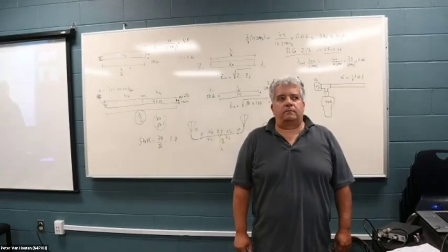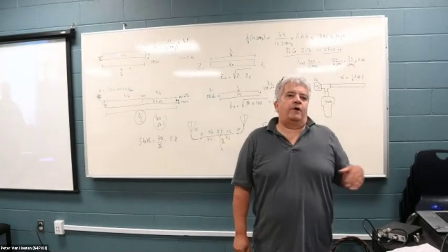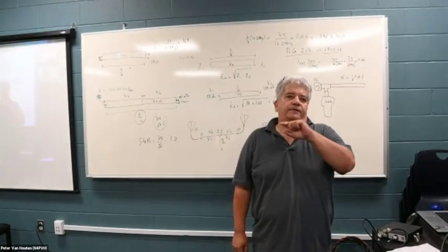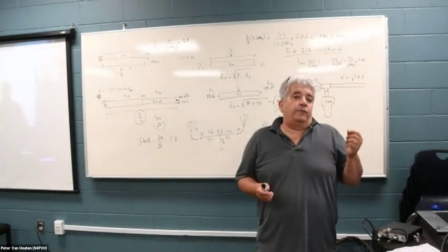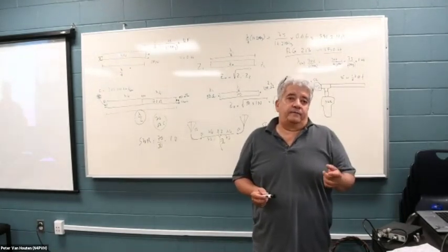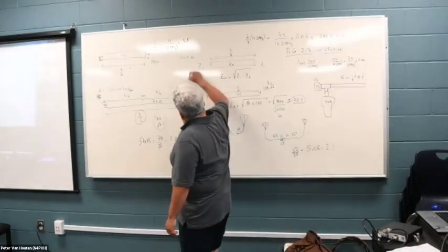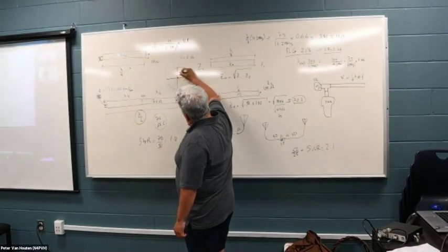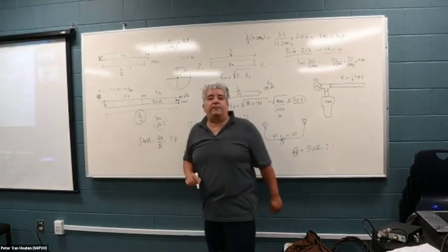And I could explain that, not today, with what happens with an impedance along a certain length of a transmission line with the Smith chart. But in the Smith chart, remember that if you are in the center of the Smith chart, you are looking at 50 ohms plus j0. So that's a perfect match.